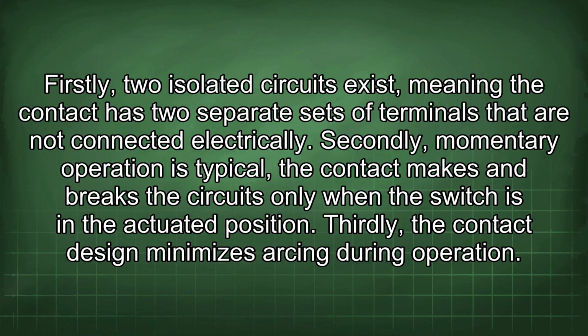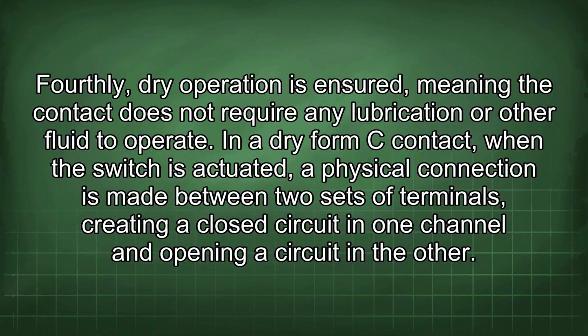Secondly, momentary operation is typical. The contact makes and breaks the circuits only when the switch is in the actuated position. Thirdly, the contact design minimizes arcing during operation. Fourthly, dry operation is ensured, meaning the contact does not require any lubrication or other fluid to operate.